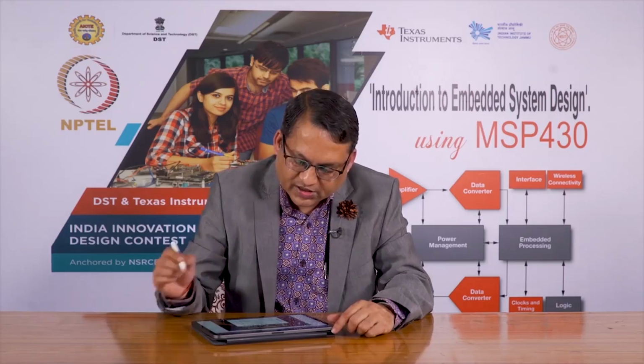But still it is a very interesting mechanism. It allows you to control a relatively large number of LEDs using few pins. If you are stuck in an application where the number of pins is very less and you want to control few LEDs, few 4, 5, maybe 10, this is a good technique, because this allows you to control a relatively large number of LEDs using fewer pins without involving additional hardware expansion technique. For example, you could use a shift register; you do not have to involve any extra hardware, and yet you are able to control these LEDs. So, this is very good for such a configuration.